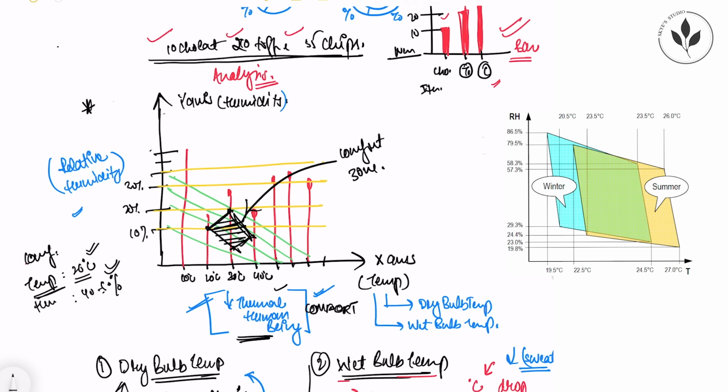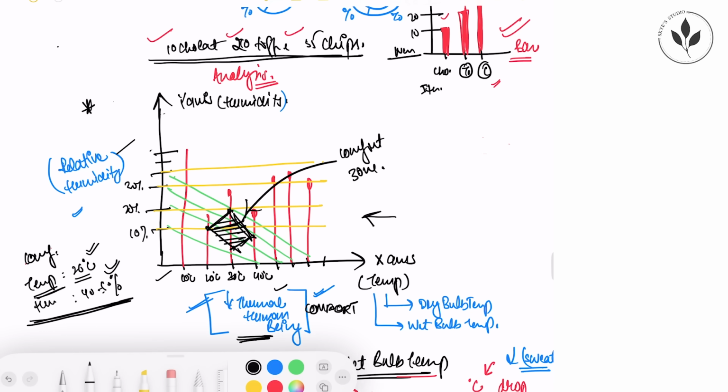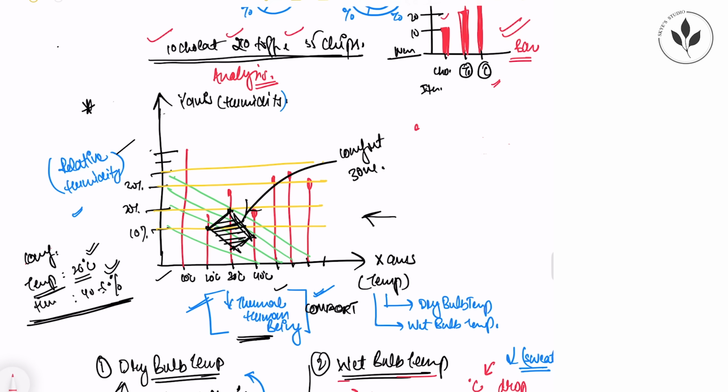of this chart. When we are getting temperature and relative humidity of a particular area, we try to find out the maximum comfort level of a human being according to the given data. And with the help of the psychrometric chart, we can help in planning, and as architects, we can have solutions related to energy efficiency in our building.